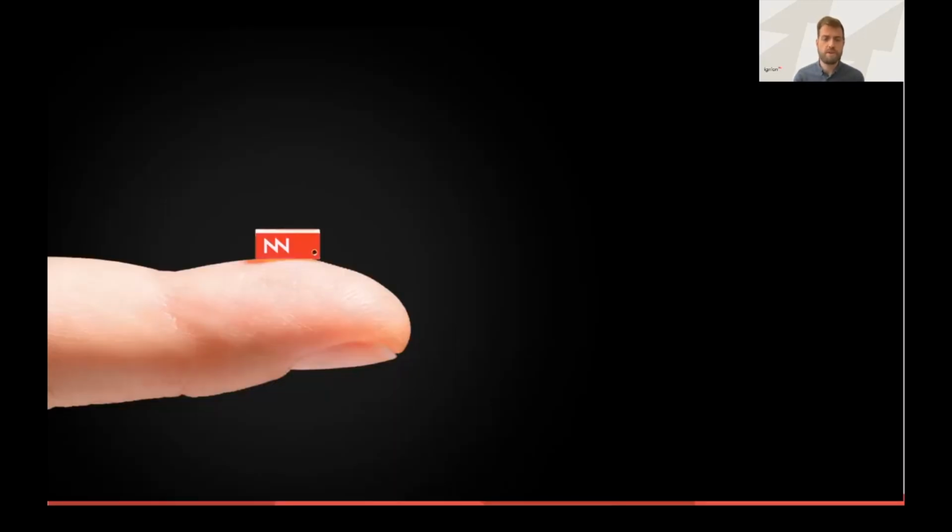So the virtual antenna, you see one of them on this picture. It is a unique technology. It is a non-resonant antenna technology, meaning that the antenna itself is not resonating and is making the whole electronics design resonate. If you compare to traditional antennas, they all resonate. This one doesn't. And this gives a unique suite of flexibility and characteristics and benefits that have not been possible before.